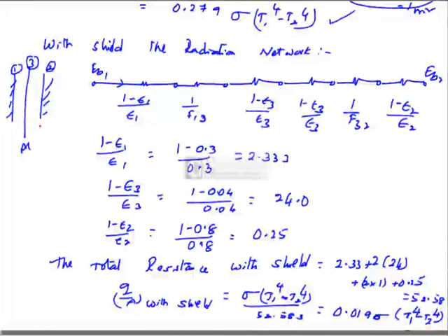That will put up higher surface resistances in the circuit, thereby radiation heat transfer will get reduced to a greater extent. Please note that here the heat transfer rate is reduced by 93.2% just by keeping one shield having very low emissivity or very high reflectivity. Hence the problem.